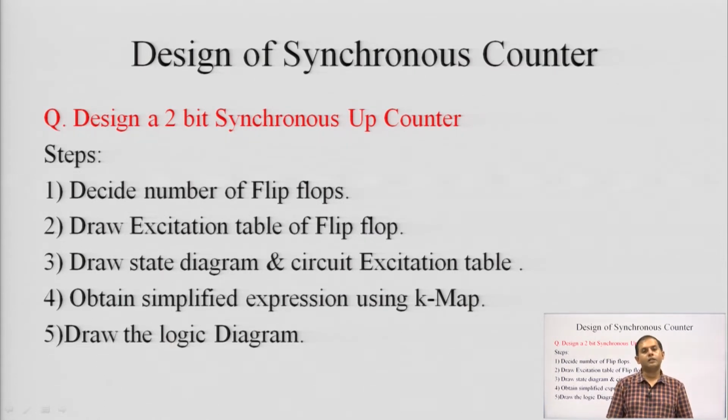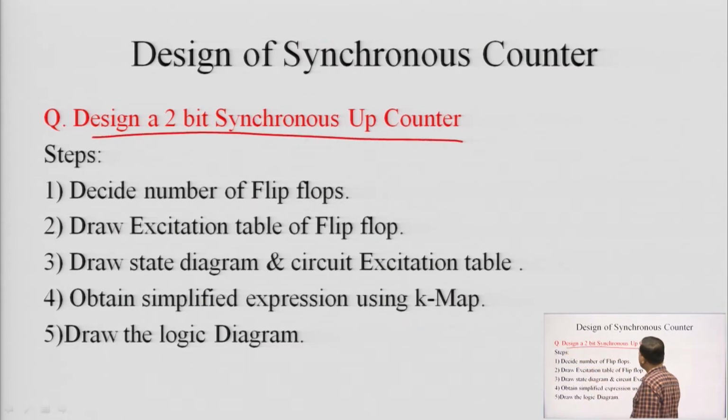Synchronous counter means the same clock pulse is given to each of the flip flops at the same time. So, here we have one question: design of a 2-bit synchronous up counter. Here every point is very useful. Synchronous means all flip flops will be given the clock pulse at the same time, and up counting means it will be going from 00 to 01, 10, 11, like that, up counting.